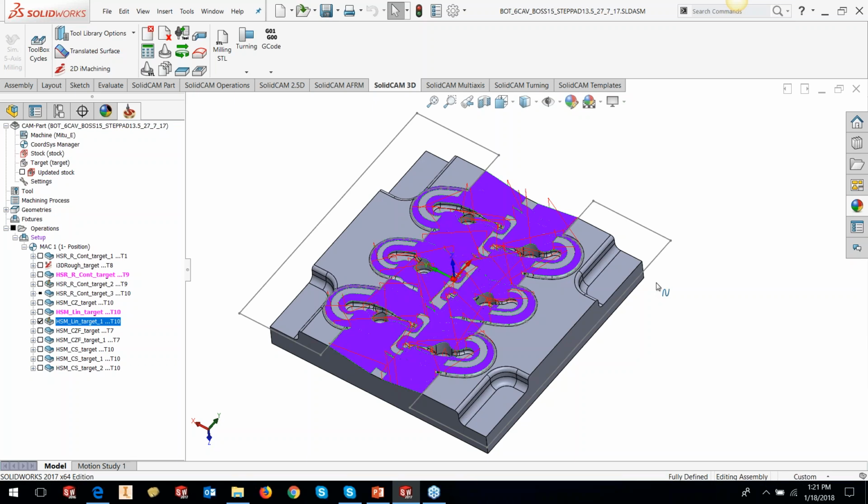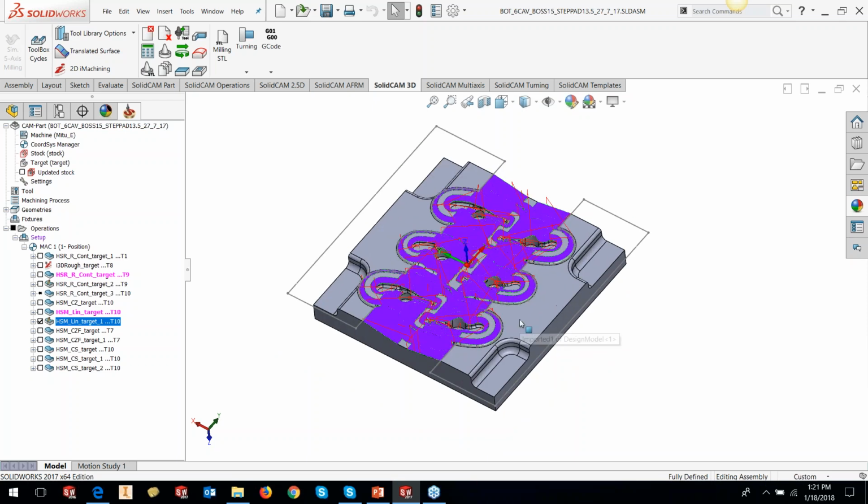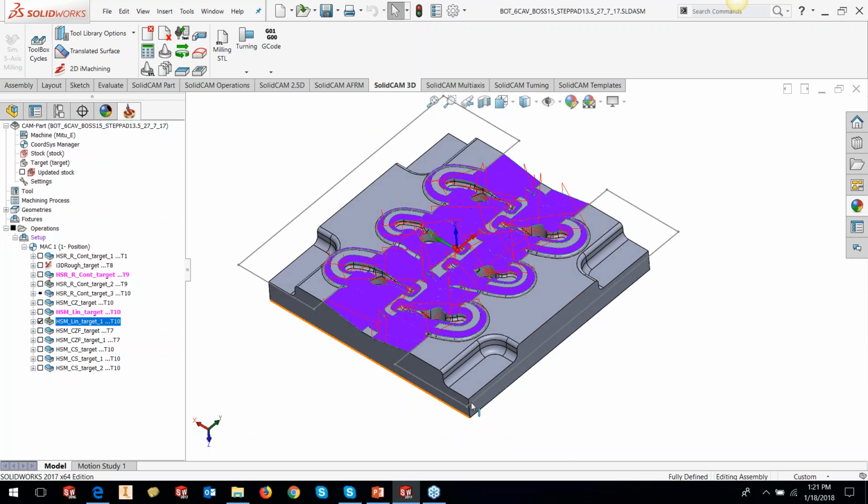While I was presenting this webinar, I thought of other areas where you could use this. In many cases, for example, you have areas where you would like to keep a secondary offset, but currently our HSM doesn't allow it. So you could generate a complete toolpath, and in the areas where you think you need a secondary offset, you just mark a contour and chop the toolpath out, and using the same contour you generate another toolpath with the secondary offset.